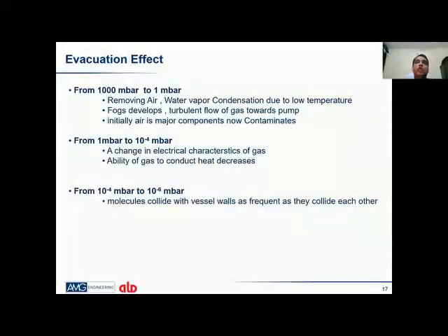So we have now seen what the different vacuum pumps are, at what level they are used, and what their cost effectiveness is. Let's try to visualize what happens when we start a vacuum pump down inside the furnace, when we have to go from atmosphere to 10^-5 and 10^-6. 10^-6 is where most nickel brazing applications are talking about the 10^-5, 10^-6 level.